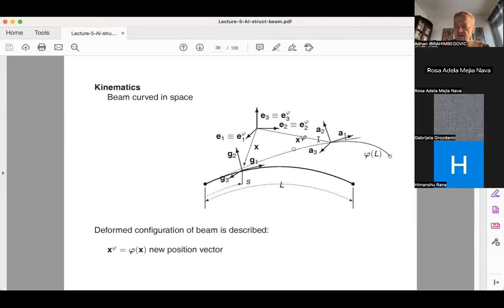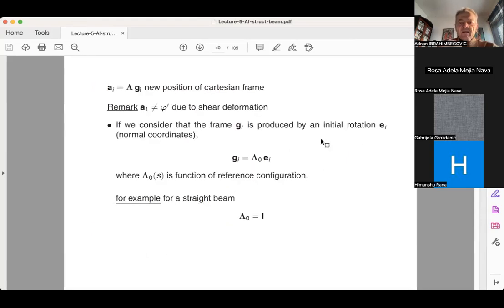And then let's say unit vectors A are in the deformed configuration, so they could be expressed with the base vectors in the global configuration, which I call E1 phi, E2 phi, E3 phi. But for any practical purposes, we said that these two vectors are chosen to be the same just for the clarity of the concepts. We keep a different symbol with the phi, having significance that you are sitting in a different configuration. So basically, this local Cartesian frame, as I said, unit vector brought to unit vector,